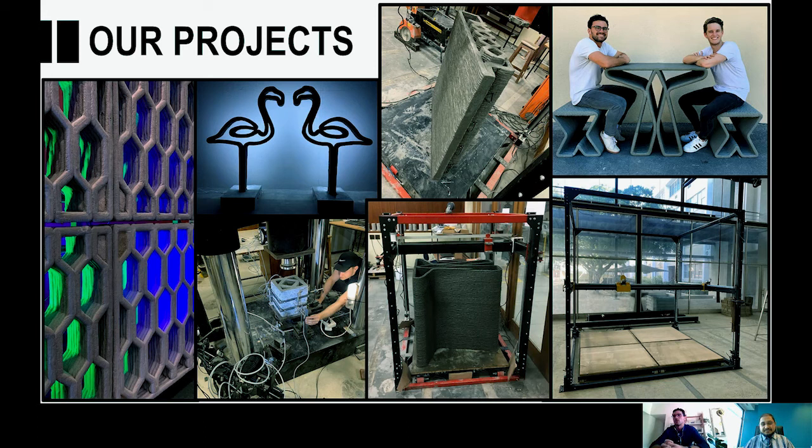Now, this is one of my modular components that I've designed. Essentially, this is one of those building blocks that you referred to that would make up a shear wall to resist your induced loading. So this is a lateral resisting member, and it's designed as a bending dominant wall to then obviously dissipate the energy in case of a seismic event.